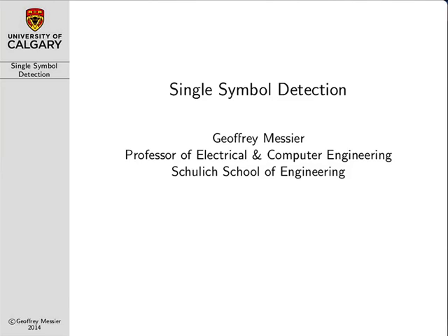In our match filter module, we talked about how the digital communications receiver is basically divided into two functional blocks, the demodulator and the detector. The demodulator, which was essentially our match filter, its purpose was to take the received analog signal and convert it into a received signal vector at a rate of 1 sample per symbol, and to do it in such a way as to maximize the signal quality, which we expressed in terms of signal to noise ratio.